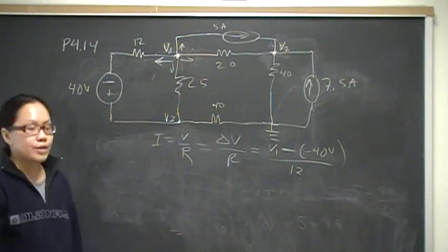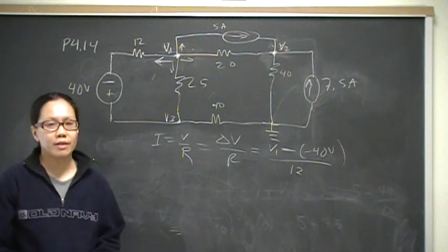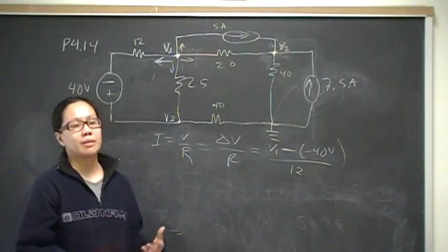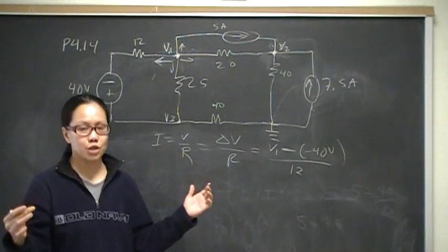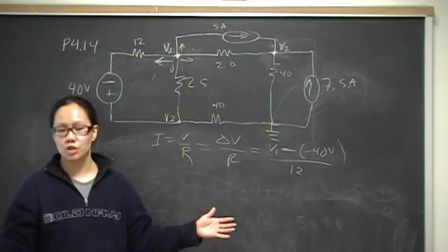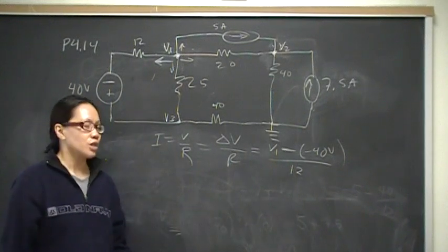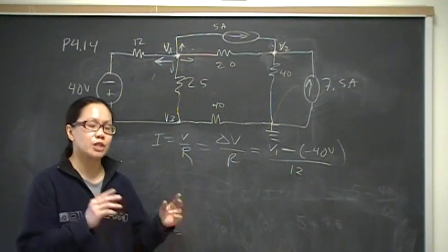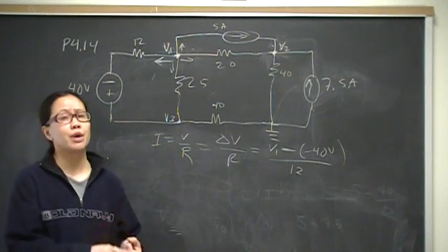Okay? So the biggest mistake that people make when they're using the node voltage method is when they get into a rhythm of taking this voltage divided by whatever is the circuit element. And then they forget to look at the circuit element, and it might be a dependent voltage source. So they'll take voltage 1, voltage 2 divided by a dependent voltage source, which is not even a number that makes sense. So remember, bear in mind that even though we're finding voltages, we are using Kirchhoff's current law. What am I calculating? It better be a branch current.